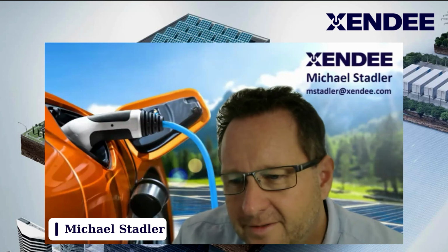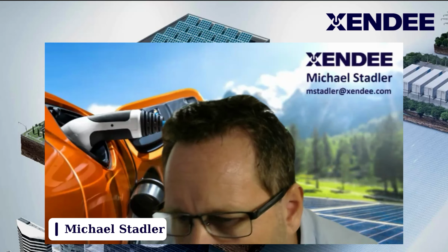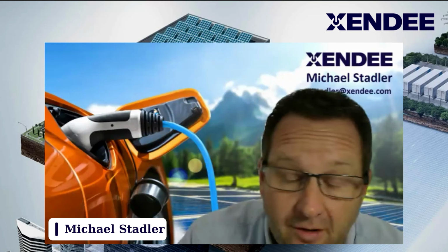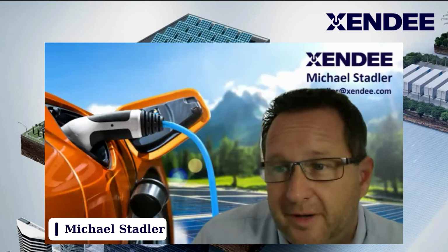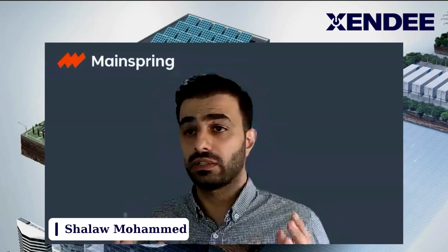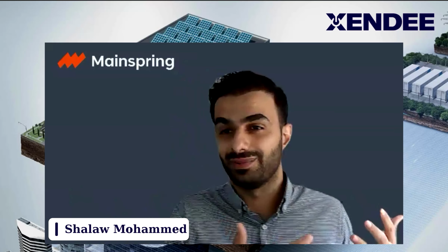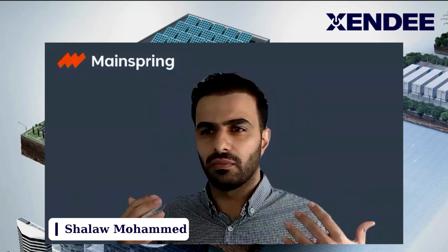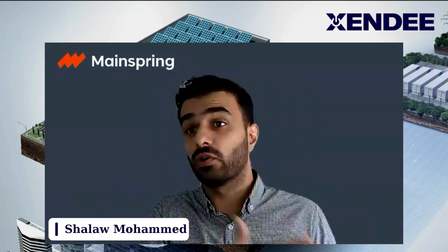So Richard is asking, what is the start time from cold start? Demand response time required is 7 minutes. So the question probably is if you're fast enough to do a cold start and do demand response. Yeah, I think we are. And actually, this is a relatively fast start compared to some other technologies. It's not a diesel engine with a 10-second start, but it would roughly come up to rated speed, voltage, and frequency within 5 minutes from a very cold start.